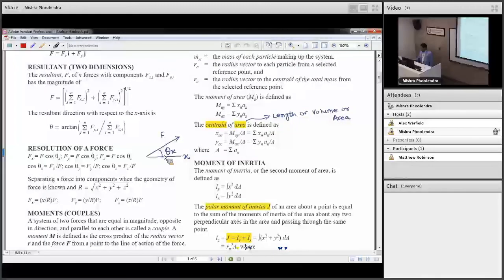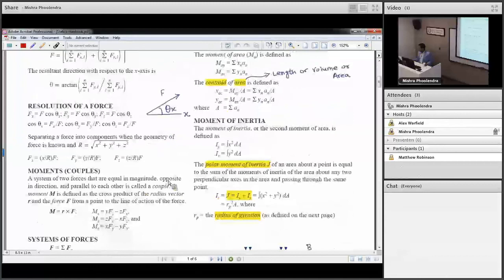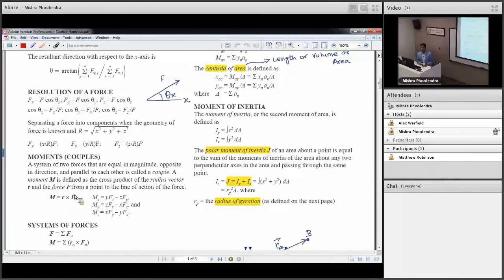This also gives you another important definition, which we briefly used in the vector portion of the math section last week. You can generalize this to 3D. We can define a force by its magnitude and direction. For direction, we define how much angle it makes from the x-axis, the y-axis, and the z-axis. Those are called the direction cosines: direction because they give you the direction, cosines because we find them using cosine. We take the x component and divide by the magnitude. That's what these relations are telling you. Cos theta x, theta y, theta z are the angles from the positive x, y and z axes. Positive is really important, it's not from the negative. If you use the negative, it's 180 minus theta. Using that, we can find those direction cosines if you have to.